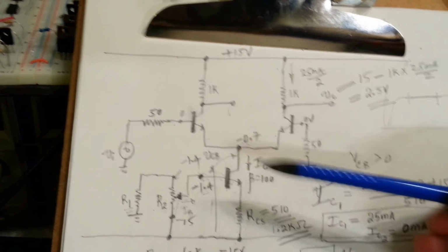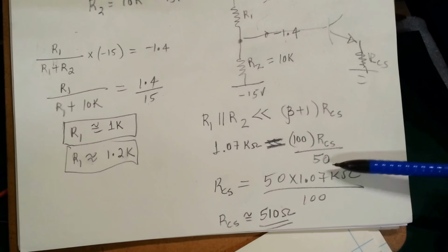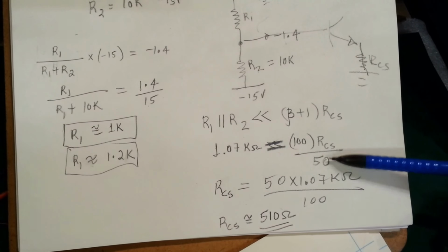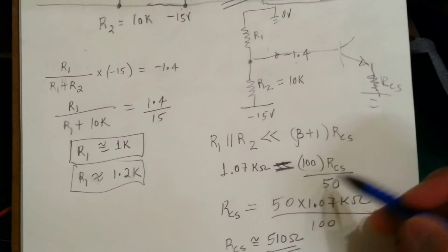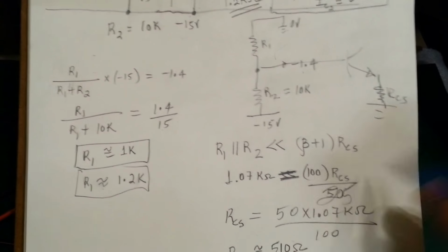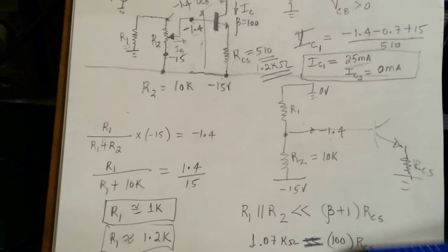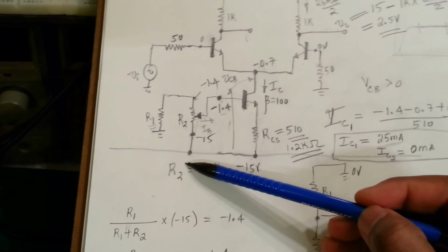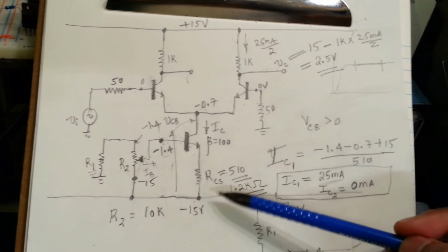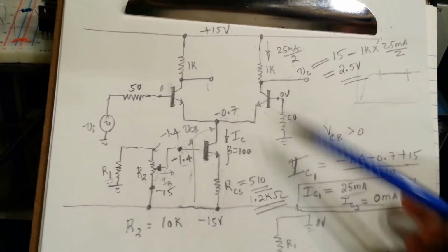That's what I did, and it won't affect the calculation that we've done here, because we've taken the liberty of using 50 times here. So all we have done is this factor becomes 25. That's what I did to get that resistor, so it's okay. So we still are able to ignore the base current compared to the current that flows through here, so we're still good. So I've made sure that in my design RCS is 1.2 kilo ohms to reduce the current.